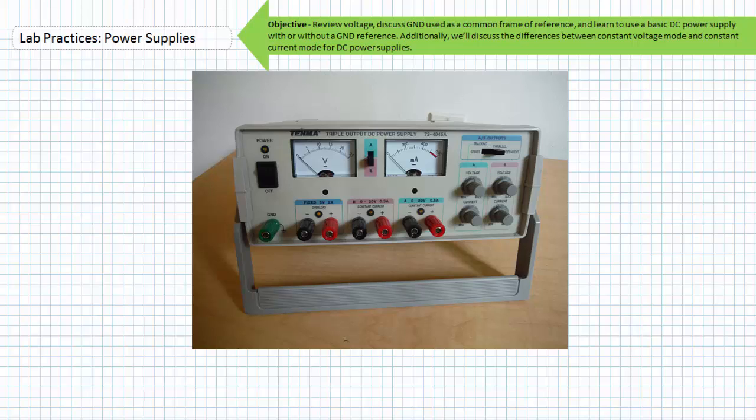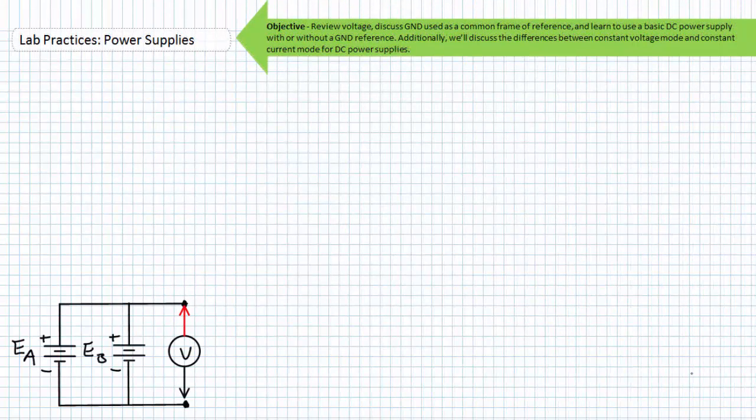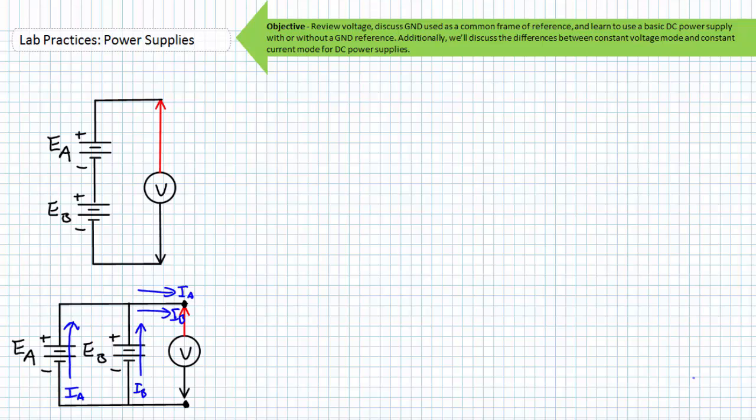When the selector switch is in the independent position, the A and B terminals are exactly that, totally independent of one another. If you switch over to parallel, A and B are placed in parallel with one another, with the same output voltage, however with an increased output current maximum. If you switch over to series, A and B are placed in series with one another, with increased output voltage and the same output current.